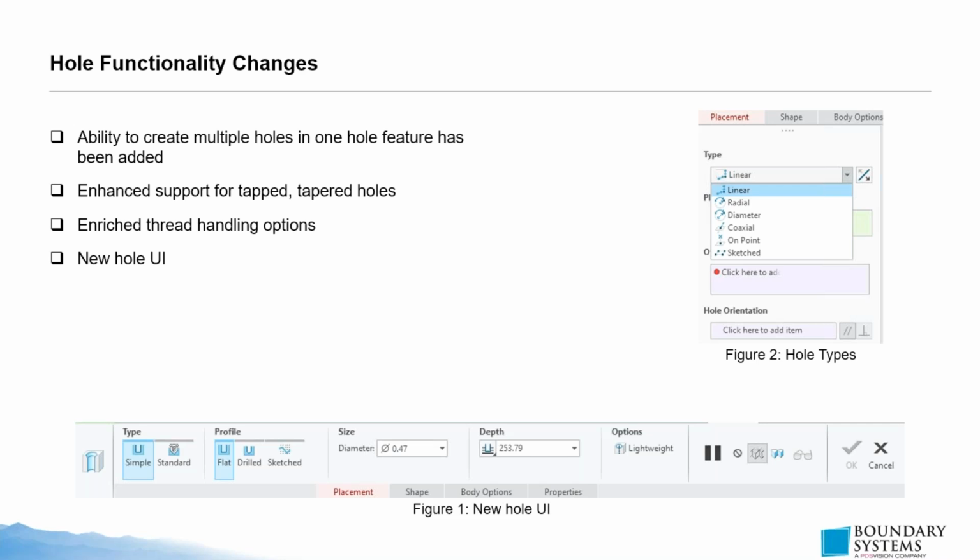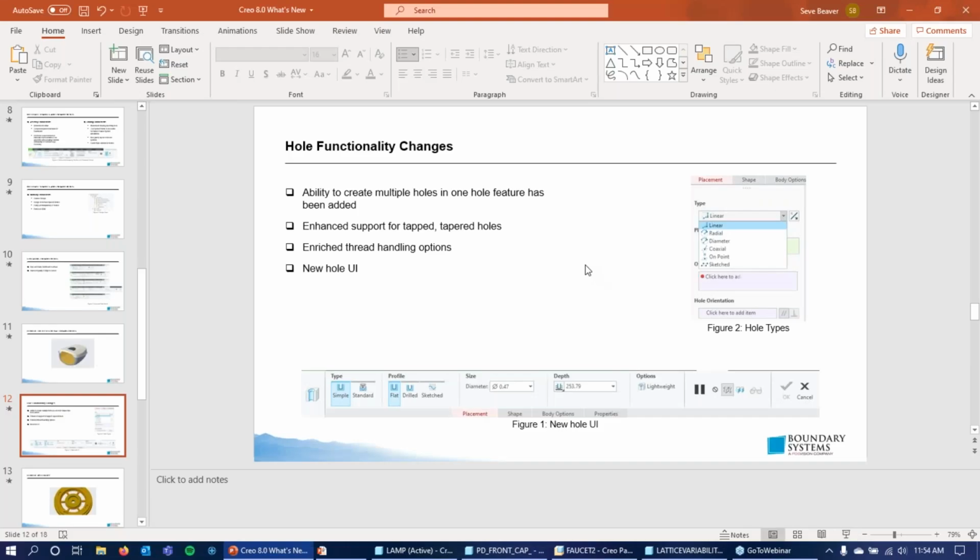Additionally, we have enhanced support for tapped and tapered holes, enriched thread handling options, and the ability to create multiple holes in a single hole feature has been added. So this is going to be really great for anyone who uses a whole lot of holes in any kind of set pattern. So I'll go ahead and show this new functionality as well.